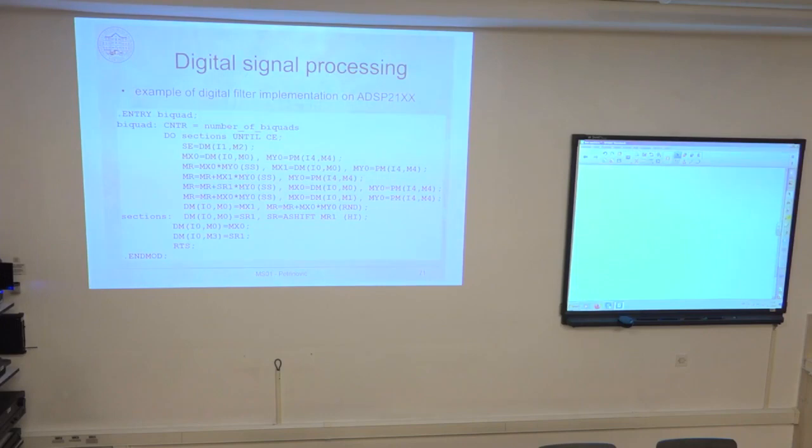But as soon as the signal frequency is higher, not only maybe 20 kilohertz as an audio signal, but something even higher than that, video for example, then a sampling rate of 44.1 or 48 kilosamples is insufficient. You must use a faster AD conversion rate.